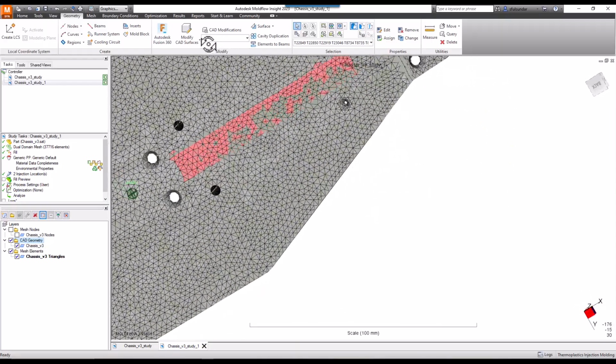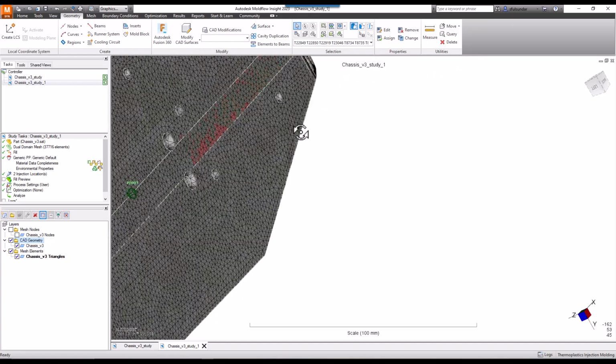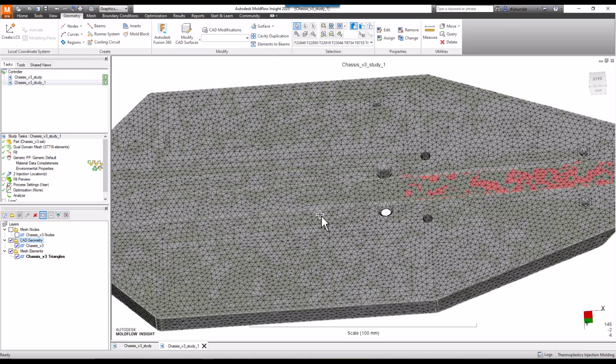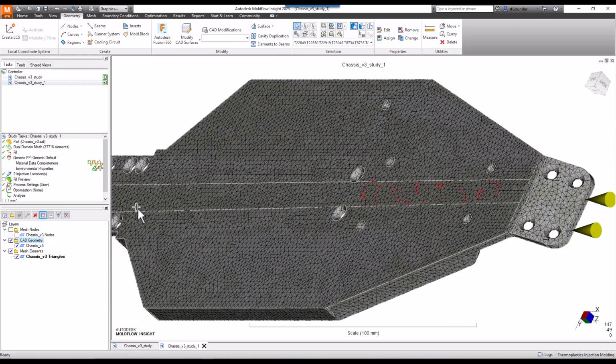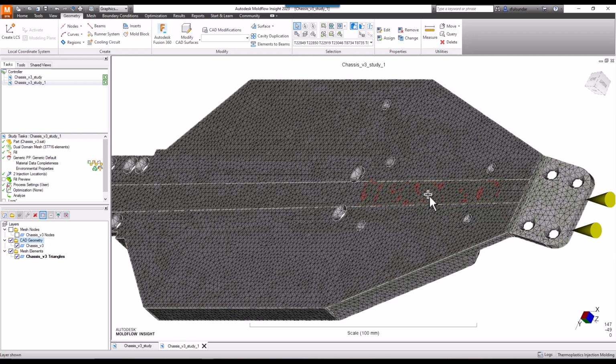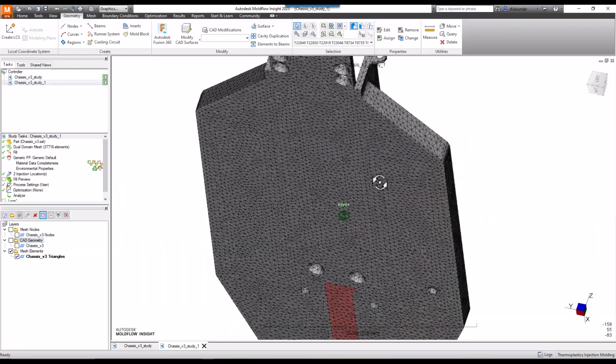On the back side, just select the very similar elements, and you can see that for the rest of the face as well, the elements are falling in line with the created splitter face. Here I have created a coarse mesh, but if you want, you can create a much finer mesh and the elements will be much better aligned compared to what you see. But this is the best way.